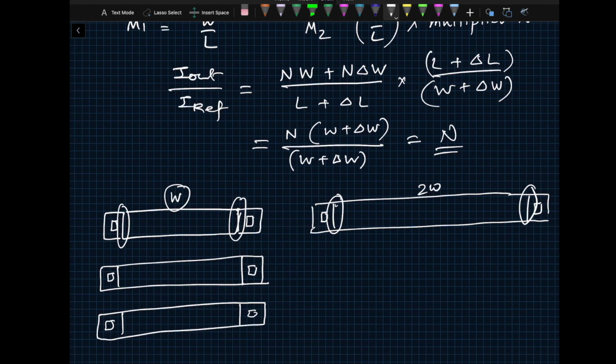Instead of just scaling the area of the capacitor, if you want really exact capacitive scaling, let's say you want a ratio of 10 between C2 and C1, then you don't just increase the area of C2 by 10. What you do is you make one capacitor C1, and then you stamp that capacitor 10 times to get your 10 times C1. So this particular philosophy, you use it for every component that you would be laying out on the chip. And these are very specific when it comes to chip, because you're drawing all these devices on the chip and you would like them to match very well.